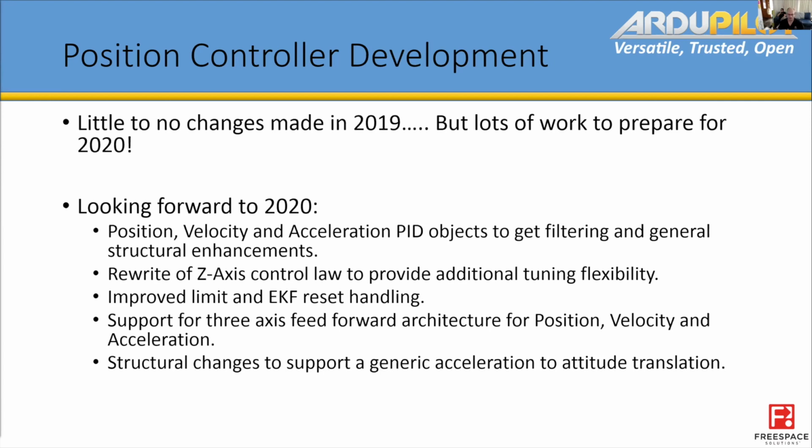Something like Sub, for example, has roll, pitch, yaw, and then it's got thrusters, so it can be upside down and cocked off to one side and still just thrust north. So it allows a more generic vehicle-specific translation there. That would potentially allow Sub, for example, to run a 3-axis acceleration PID loop on its linear thruster actuators.